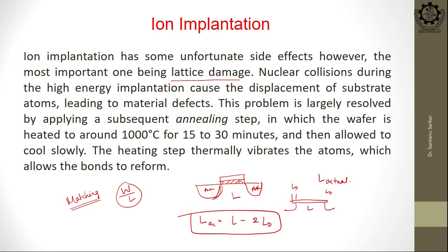One is physical uncertainty between two identical transistors, doping uncertainty. Different positions may have different doping profiles, and gradient error. Gradient error will also introduce voltage error. So, all of these will cause a mismatch between two identical transistors, which will introduce error in your design.